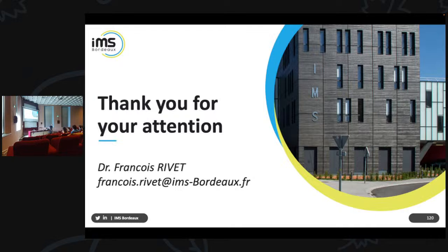Yes. About the Walsh transform, so it's a directly discrete transform. Yes. So it's like a Z transform or DFT. Yeah, kind of. Is there a continuous equivalent? No. And if I understood correctly, you use the Walsh basis because it makes complexity lower, and you need that from the Volterra series. Yes. The Volterra series will describe the nonlinearities of the PA. Yes, and we have translated those series into the Walsh basis.